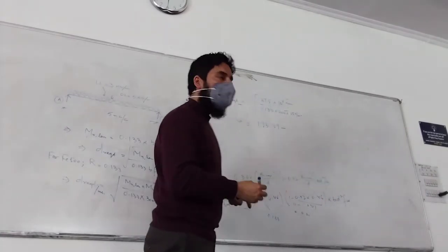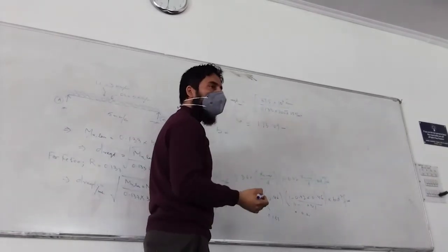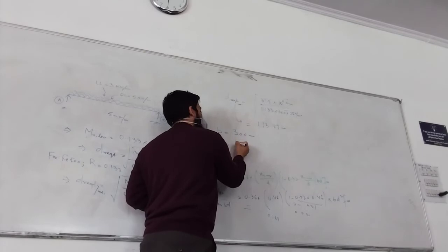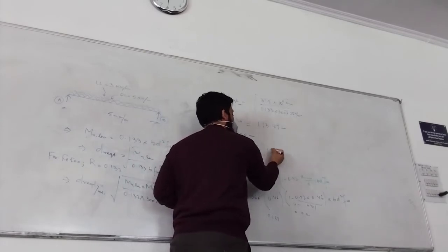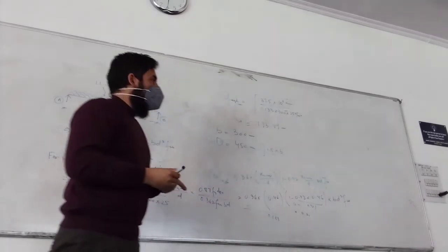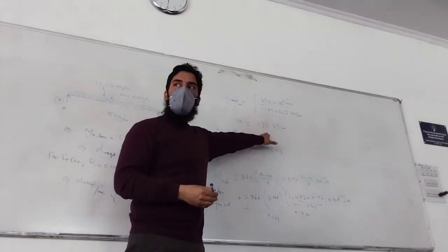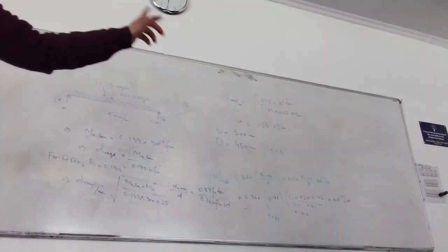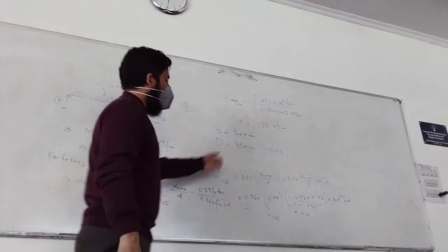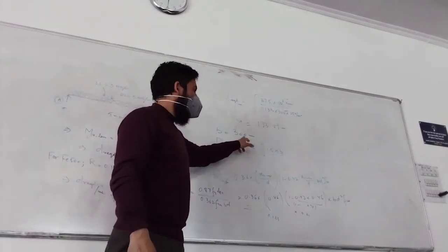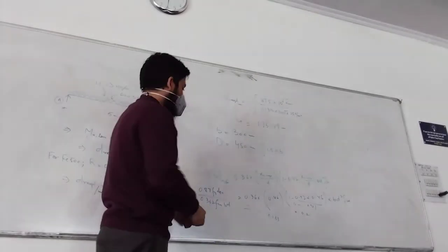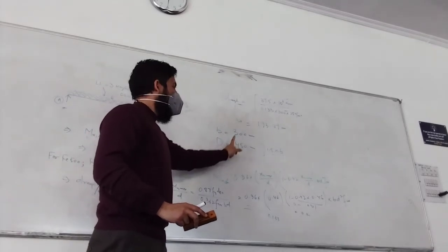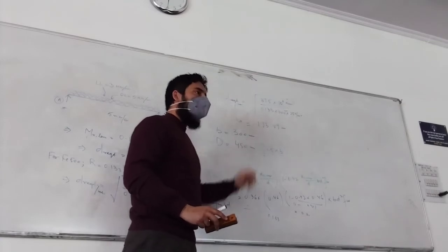But when I was calculating the value of B just now, what was B that I gave? 300. What was D that was coming? 450, when I multiplied by 1.5 times B. But how much do I need? I need only 193 as D minimum for the section to be balanced. So I'll revise my design. Understood? Now I have to revise my design. Why? Because I need only this minimum and I am providing 450.